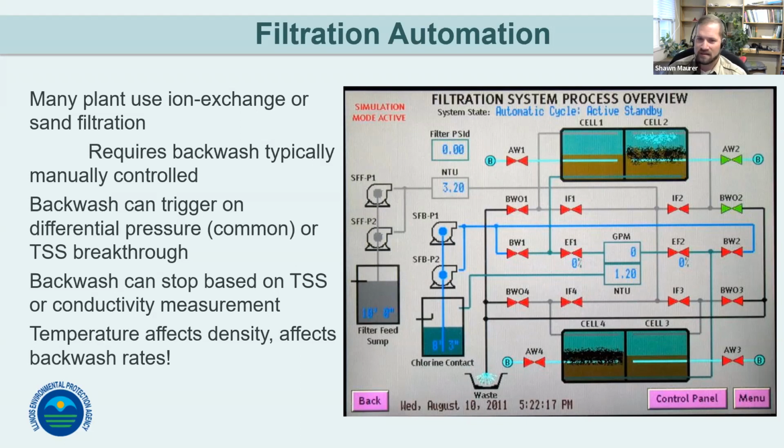So a couple of additional sensors on the system and a little bit more automation isn't incredibly expensive for these systems, especially if you've already got differential pressure control tied to a SCADA system. It's a little bit more expensive if you're doing all this manually. But there's a significant payback and a significant regain of your finished water. You're not losing as much in the process.